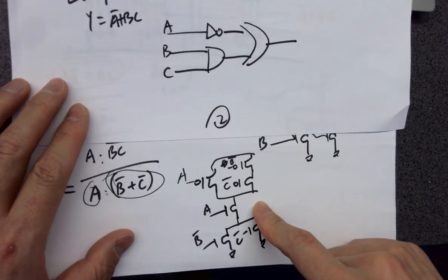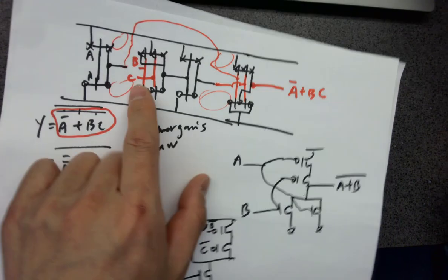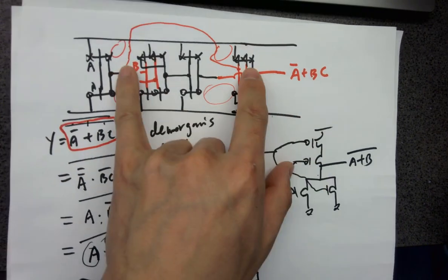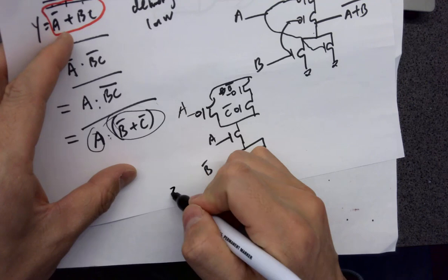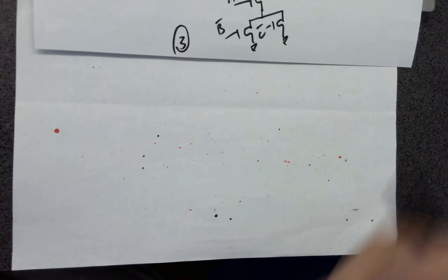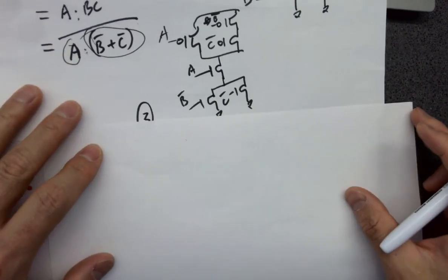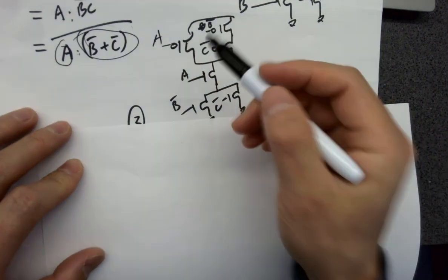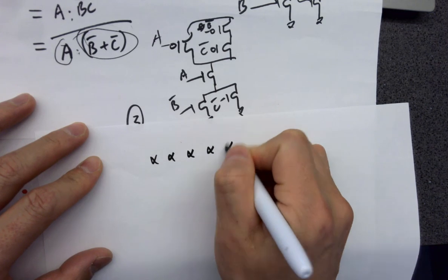And you can definitely simplify your layout as well, because you know how to do it using stick diagrams. Okay, so you don't have to draw every single transistor separately, like this. It's taking a lot of empty space. So in that case, let's just convert this guy to its stick diagram and see how much we can simplify the layout to save space, because space is so expensive on the chip. So how to convert this one to the stick diagram? 3 transistors on top, 4, 1, 2, 3, 4. So we need 1, 2, 3, 4, 5 nodes.